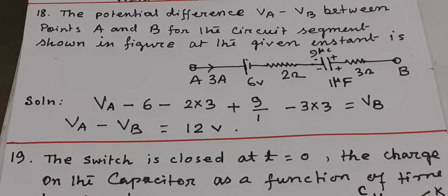capacitor shown in opposite direction. So here we can do this will act just like a battery, negative to positive, like that. It will be 9 microcoulomb divided by 1 microfarad. Micro gets cancelled, coulomb by Faraday will give volt. That means 9 volt will be added here.